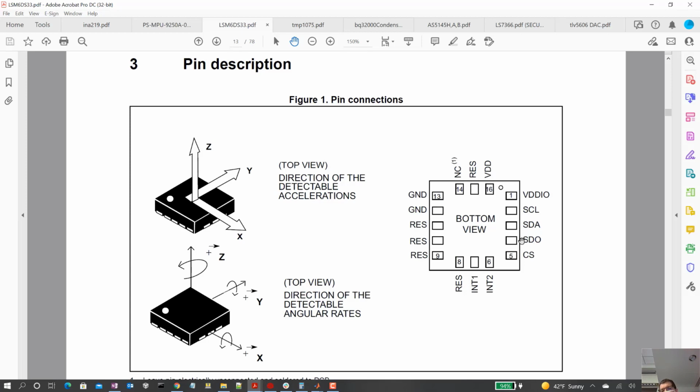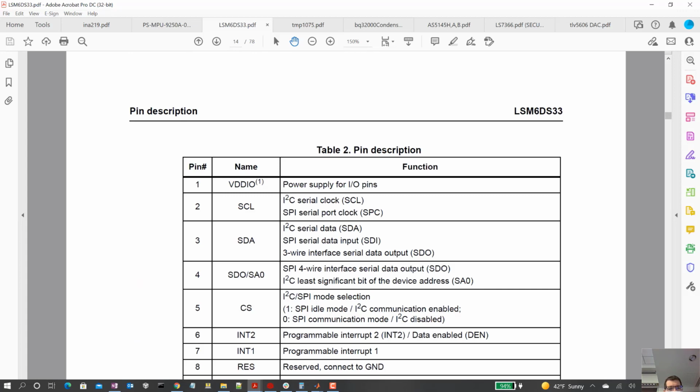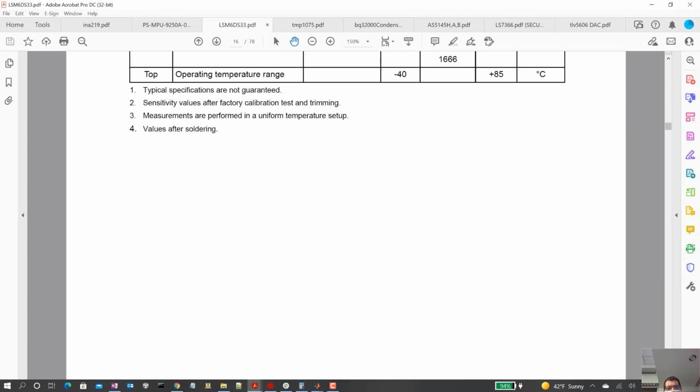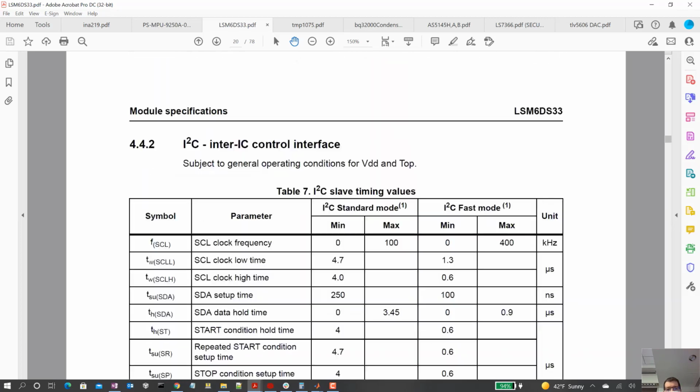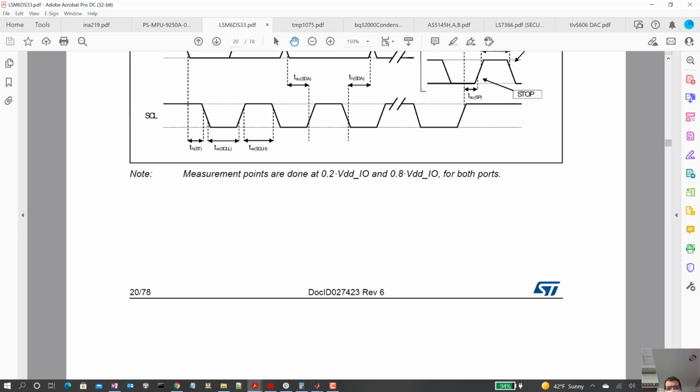There's probably a default way you have to wire these pins down here, these 2 probably, so that it knows to use I2C and not use SPI. I'm sure there's something like that in the data sheet. So we can interface to those. Now, I thought it had a way to do its address, but we'd have to check that a little bit closer. But anyway, there's probably a way to set its address between a couple different addresses.